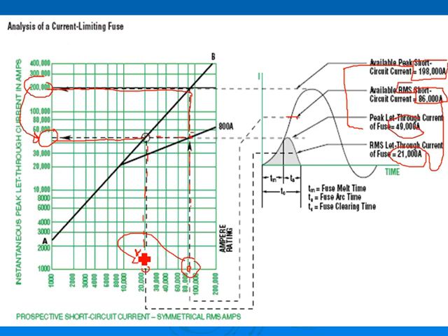And arc flash, when we run arc flash analysis on the system, it can take you from category 4 all the way to category 1, just by putting in a current limit fuse. Any comments, any questions about current limit fuses? If you have a situation where you need to limit the current in your system, a current limit fuse will be your baby.